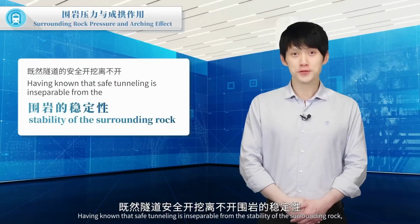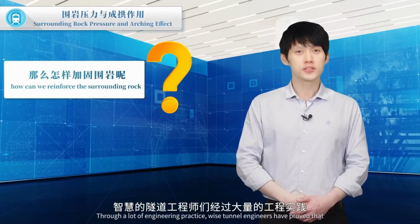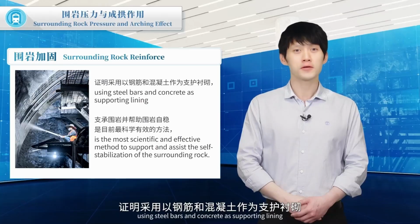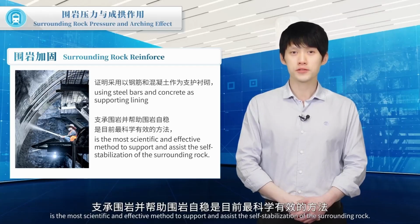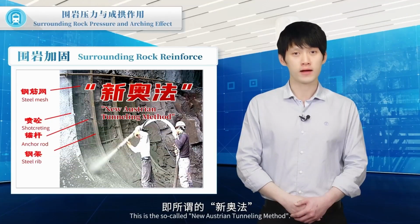Having known that safe tunneling is inseparable from the stability of the surrounding rock, how can we reinforce the surrounding rock? Through a lot of engineering practice, wise tunnel engineers have proved that using steel bars and concrete as supporting lining is the most scientific and effective method to support and assist the self-stabilization of the surrounding rock. This is the so-called New Austrian tunneling method.